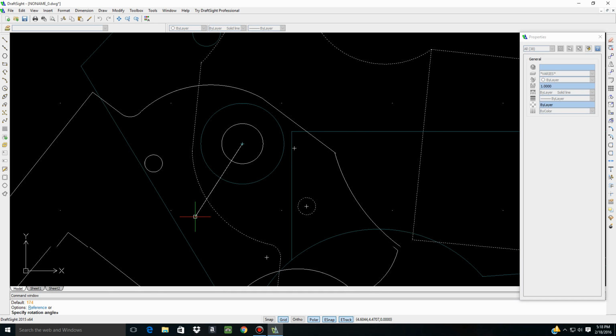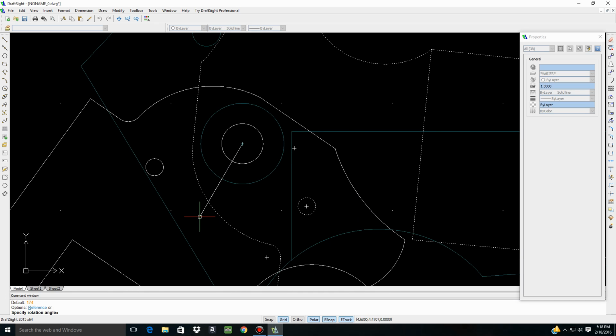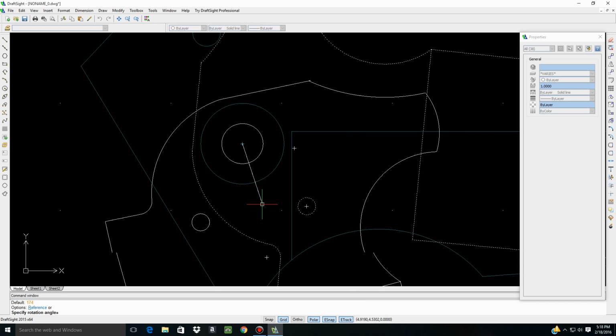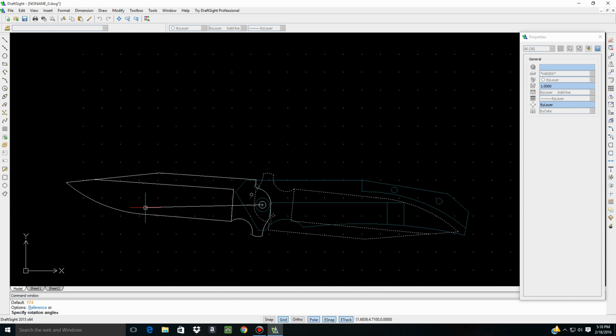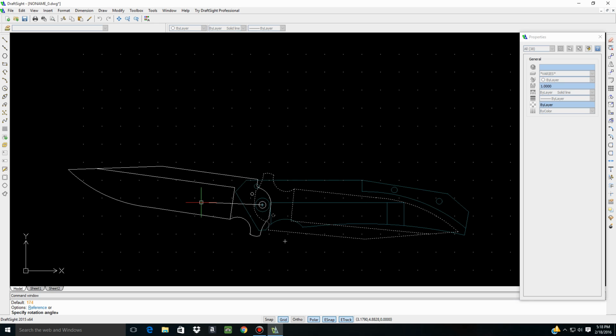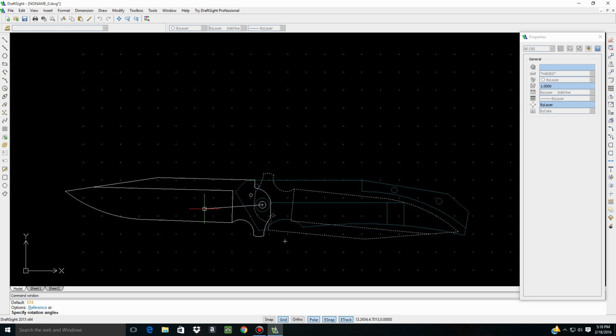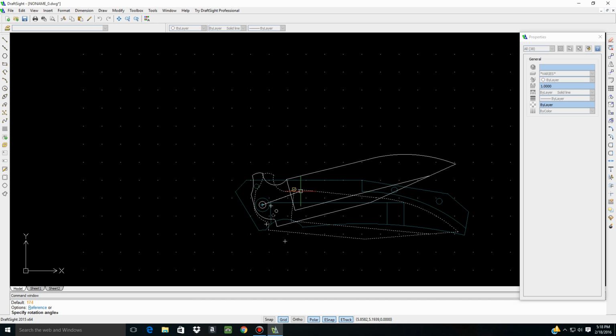You don't want to have to close the blade this much before your detent ball hops on the blade. That's way too much. It's going to make for a very clunky locking mechanism. So you want that ball on the blade as soon as possible. So right here, whoop, and we're good to go.